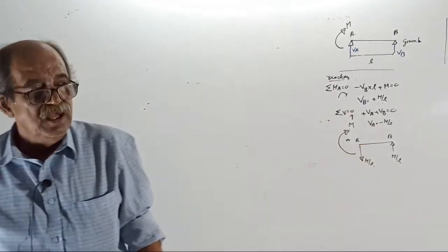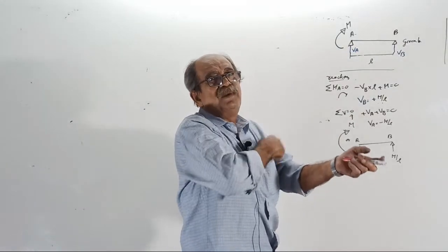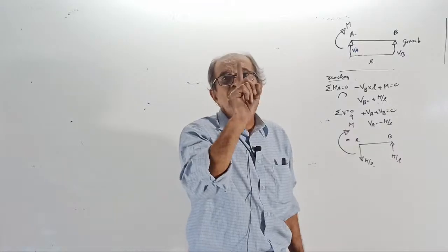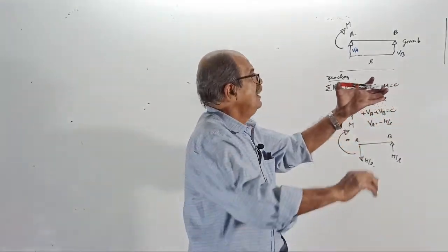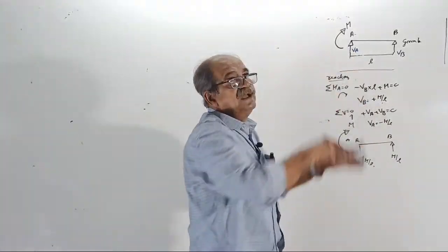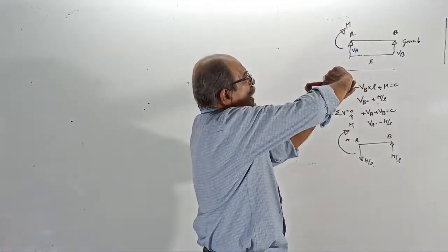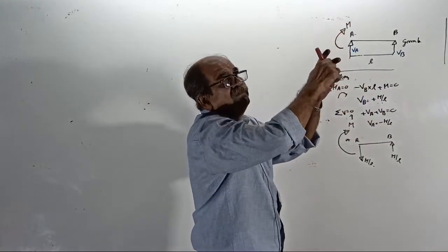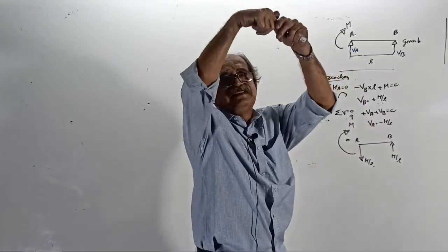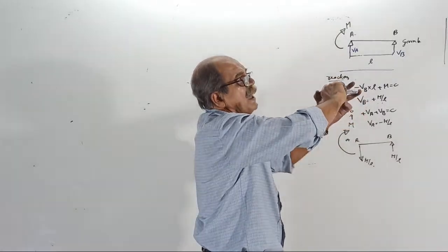First, I told you one easy method there. See, you take the beam free. When there is only one couple, then couple is M, and both reactions are M by L. See, if you apply a couple, one side will lift. Where lifting will come, to prevent it, the reaction is down. See here, if I apply clockwise, left will lift.